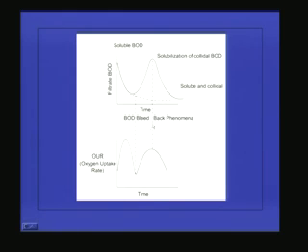So, this is known as the BOD bleed back phenomenon. If the BOD profile is like this, how does the oxygen utilization or oxygen uptake rate behave in the system? Initially the oxygen uptake rate will be 0 at the start, then it will suddenly increase, because as the BOD decreases, that much oxygen will be consumed by the microorganisms. So the oxygen uptake rate will increase, then as it comes down, this also will come down.